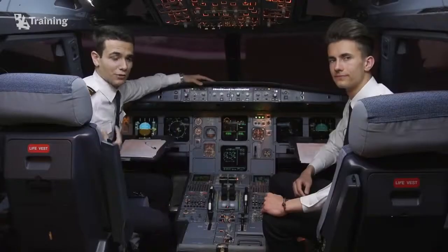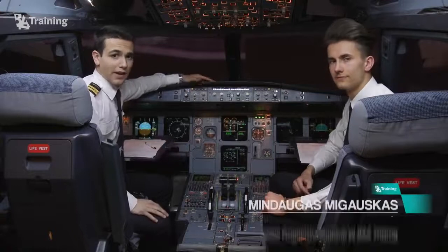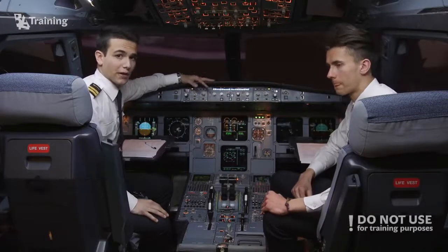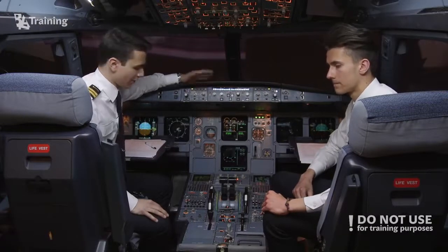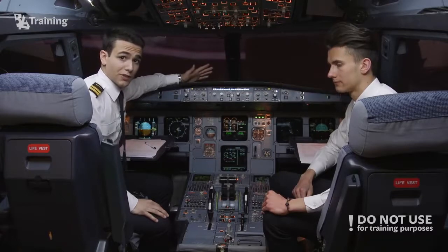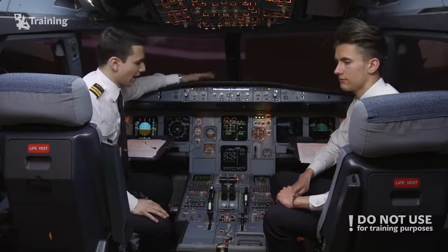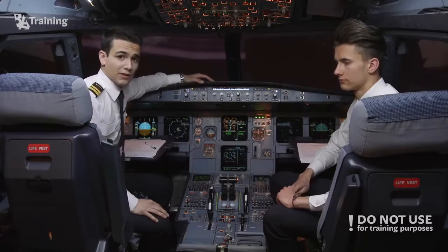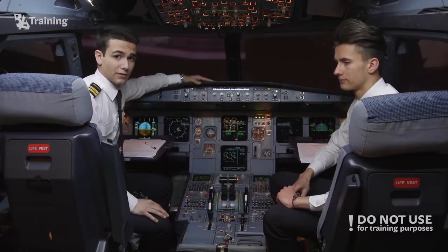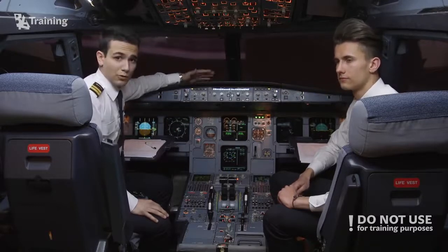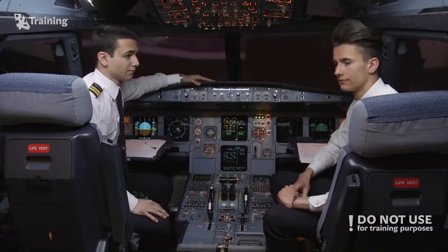Hi there, my name is Dusan, this is my colleague Mindaugas, and today we have an unusual video for you. We're going to show you how to perform a manual engine startup procedure, followed by a cross-bleed engine startup procedure in another video. What's interesting about these procedures is that both of them are supplementary procedures for the engine start, and while other supplementaries are read and done by the pilot monitoring, these supplementary procedures, because they have to do with the engine start, are read by the pilot monitoring and performed by the pilot flying.